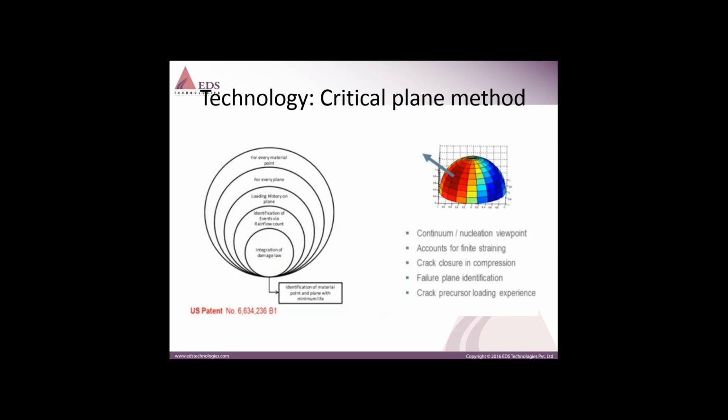We do the rainflow counting and use the crack growth rate law to calculate the fatigue in a particular direction. This will be repeated at almost all orientations to calculate the most damaging plane where the crack will initiate. This is a very good approach for identifying the crack.